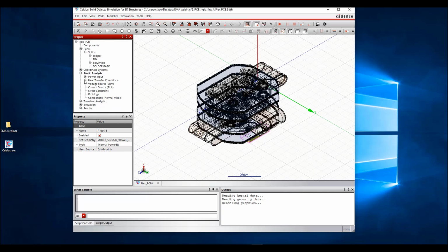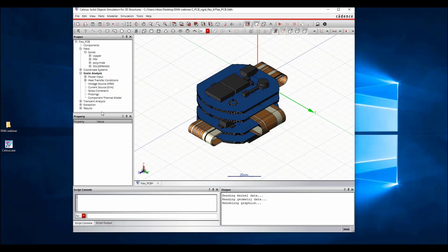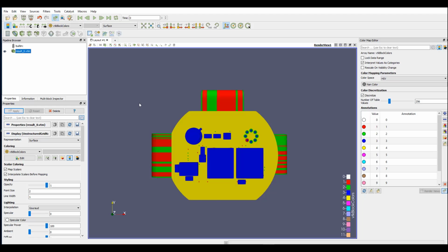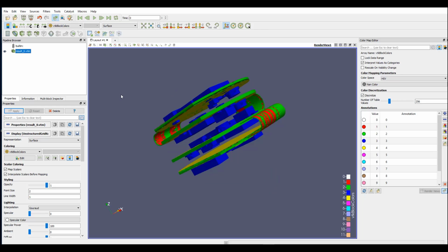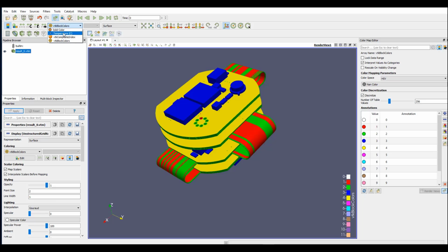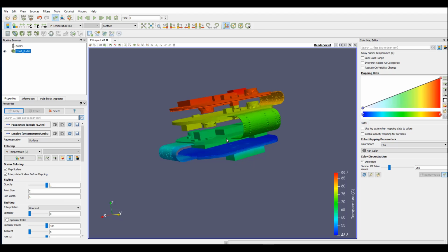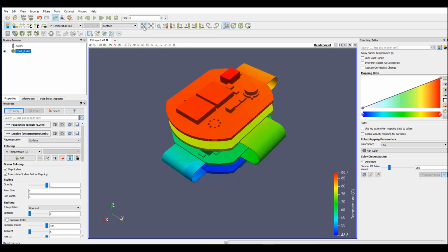Here we didn't run the CFD, but we could. For another analysis type, we could specify a heat transfer coefficient at the surfaces. It could be a constant temperature or constant heat transfer rate out of the systems. Then I'd like to show the results we already ran, just like before. Okay, that's the model itself. Then we can turn on the temperature. So that will be the temperature results. You see every detail and the component distribution, just like we have seen before.